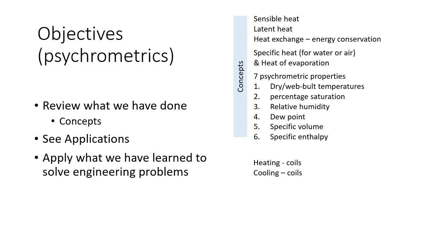Now, application. We see how the heat transfers from water into air, or from electricity into the air. Okay, and also you can see in the cooling coil how the heat is taken away at the coil by refrigerant or chilled water. So a coil is a device that allows 2 flows to contact each other.